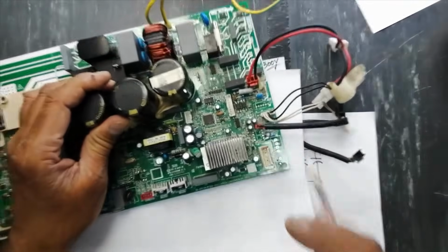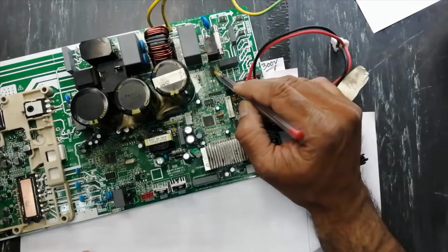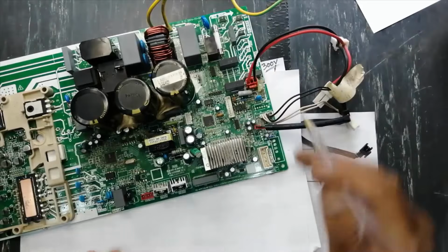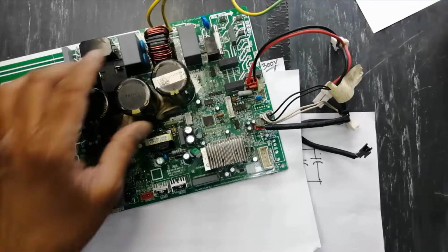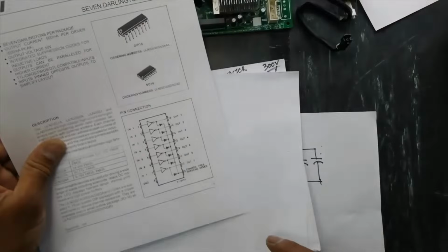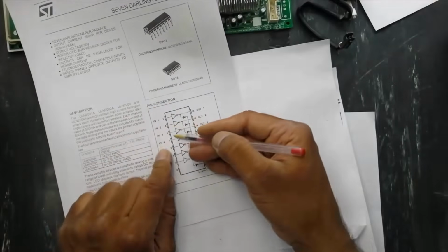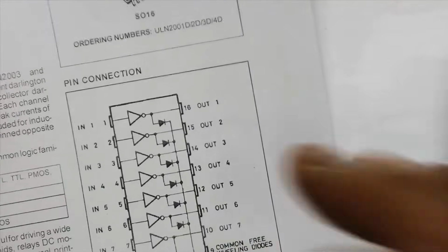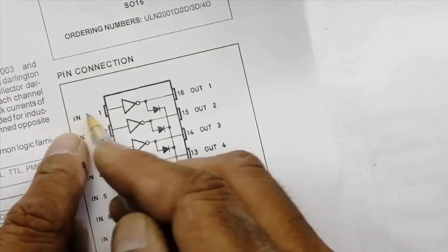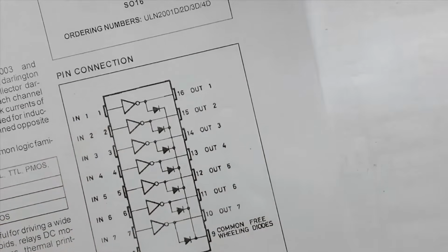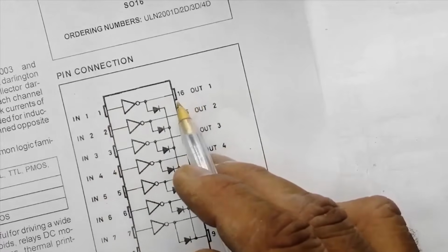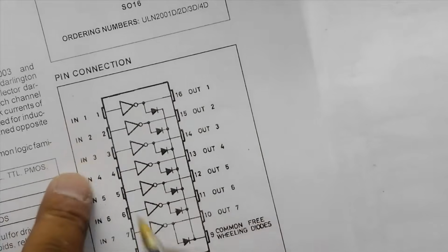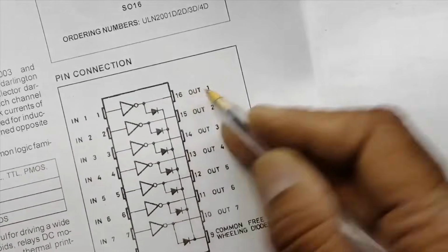And in the meanwhile, here it has ULN2003. It is ULN2003, that is a transistor array, a Darlington transistor array, that is used to switch different devices. ULN2003 takes command from the processor, then it connects ground with output number 1. Every line is, we can say, a Darlington amplifier. It is working as a switch. So all the inputs are connected to outputs.